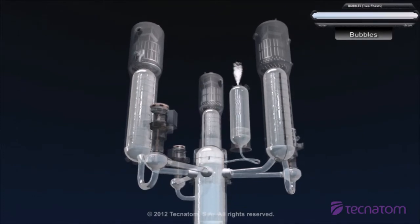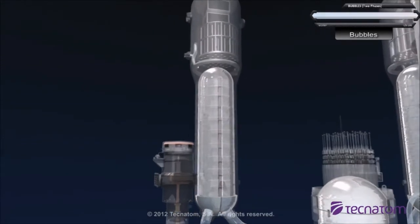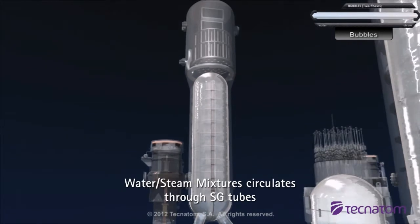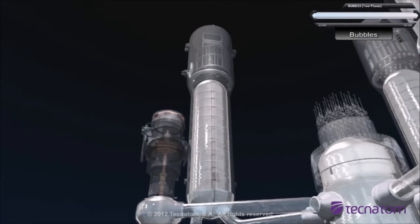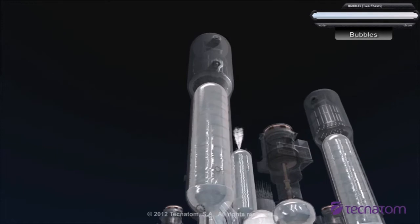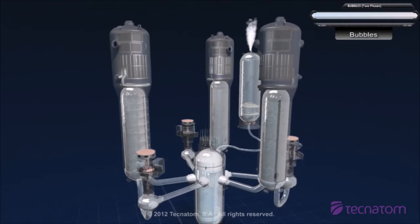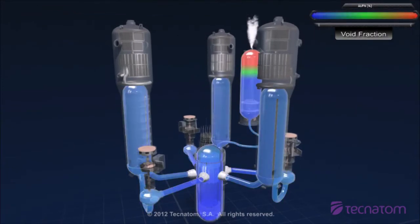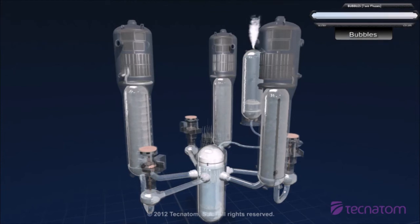More and more water is converted into steam. A mixture of water and steam circulates through steam generators, and the heat transfer lowers. Going back to the void fraction view, we see that the bubble in the reactor vessel head is expanding, and primary coolant in the hot legs is no longer in subcooled conditions.